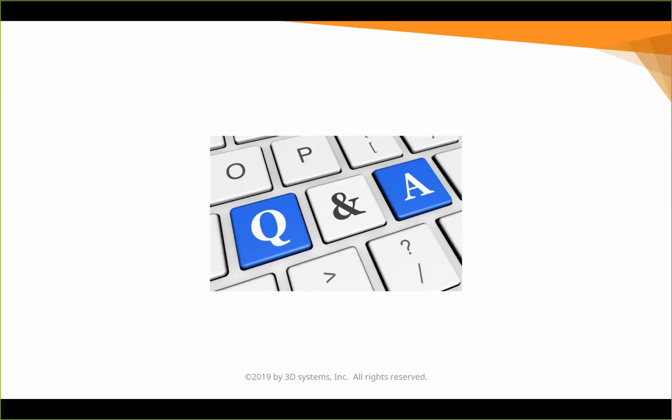Alon, I think we have a question here for you. Yes. Can AFC function only be used in rough? Can it be used for semi-finishing procedure? Right. So AFC is attached to rough procedure, rough spiral and rough parallel. Volume mill also has AFC of its own. Discussing here the AFC, we actually support all the roughing process.